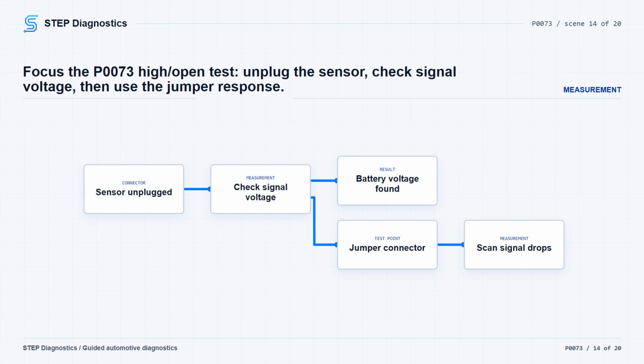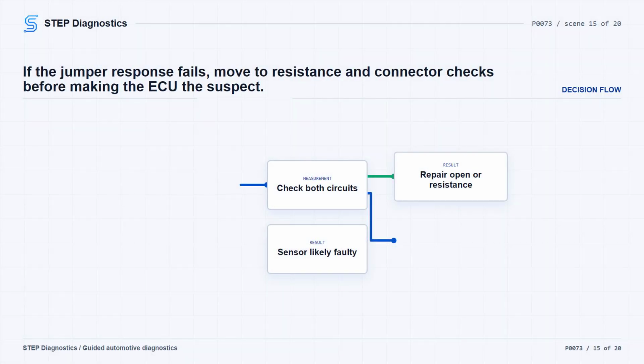If that voltage is correct and the fault is active, watch the scan tool and jumper across the connector terminals with the ignition on. Typically, the temperature sensor signal voltage should change to 0 volts on the scan tool with the jumper in place. If voltage data is not available, the circuit low fault should set with the jumper in place. If that response happens, the temperature sensor is faulty.